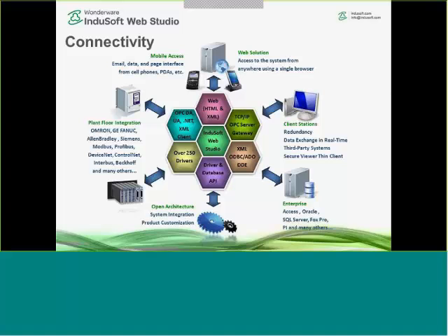We talked already about the connectivity, but briefly on the plant floor integration piece here. You can see a list of many of the common PLC vendors, but one of the unique things about InduSoft is when you create a tag in our database, it's not hard-coded linked to only one device or I/O address. You have the ability to link an InduSoft tag to multiple drivers and OPC clients. And what that enables you to do is get a lot of flexibility. For instance, you could use InduSoft almost as a protocol gateway, where you may be reading from one PLC and then sending it to another device through an OPC client worksheet or possibly another driver.